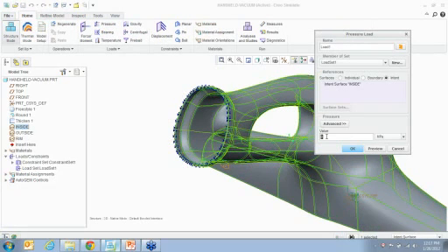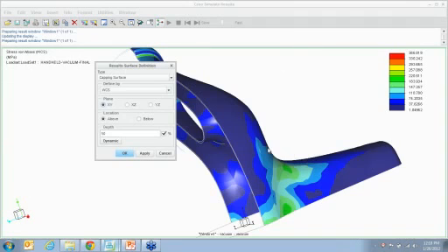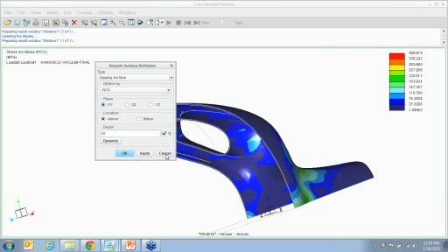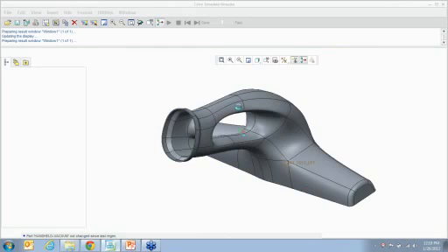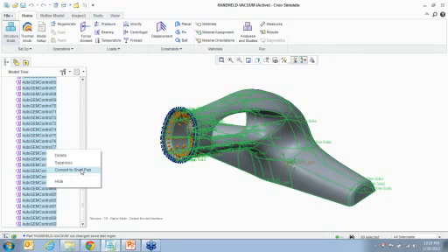We can go deformed, shell element. In order to see solid elements, we could always avoid it. The enhancement within this is that once I create this mesh, I can always go select a whole bunch of them from here and convert them into a shell pair, and then create a shell element and run the analysis.